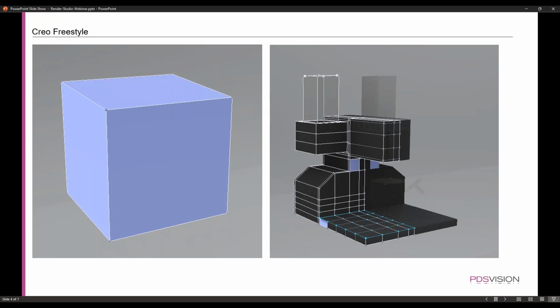You have those options as well. And then from there, you can stretch that shape. You can stretch this cube either by selecting a face, a vertex, or an edge. You can also grab a face and click extrude and add more geometry, which will help you sculpt and get even more edges and vertices to push and pull.